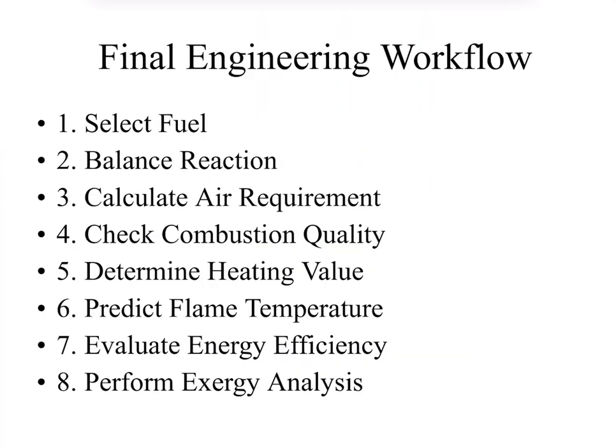The last one is the final engineering workflow. In summary, combustion analysis follows a systematic engineering workflow. By completing these 8 steps, engineers can design safer, cleaner, and more efficient combustion systems. There are only 8 steps: select fuel, balance reaction, calculate air requirement, check combustion quality, determine heating value, predict flame temperature, evaluate energy efficiency, and perform exergy analysis.